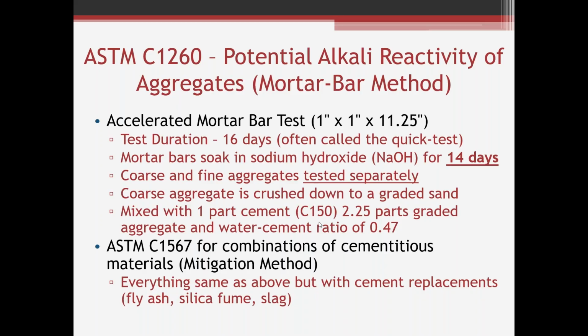And the water cement ratio is the same for every sample. So it's a standardized test. When we do it on coarse aggregate, whether it's gravel or crushed stone, we have to crush that down to a graded sand. So that sand gradation, again, is the same whether you're using fine aggregate or coarse aggregate.